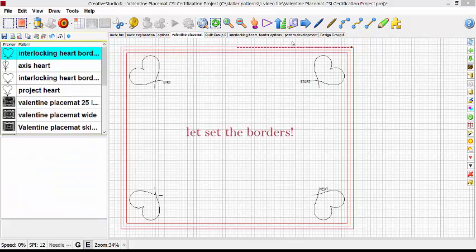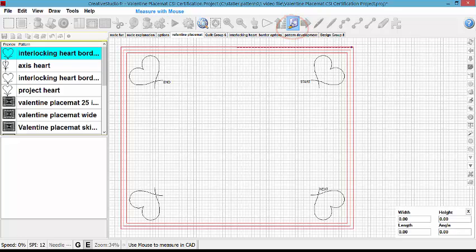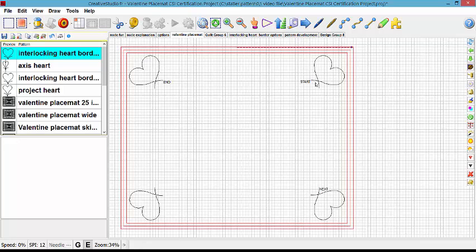Now that the border corners are properly positioned, let's tackle the border pieces. Click on the Measuring on CAD icon located on the top tool strip. A dialog box appears in the lower right corner of your CAD screen. Activate the Endpoint Snap feature located on your status bar. Click on the left border corner endpoint and again on the right border corner start point to measure. This will determine the width of the border pieces needed. Right-click your mouse to save the measurements and exit the dialog box.